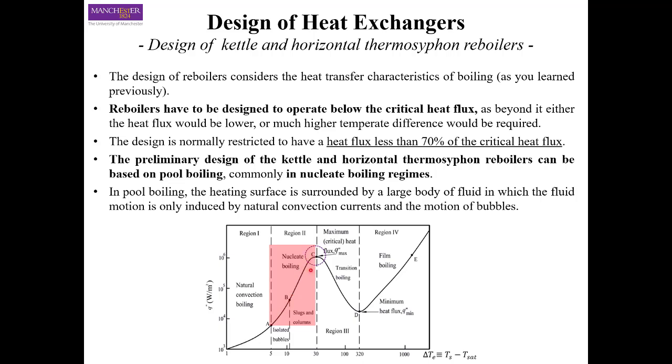When we are talking about pool boiling, just to remind you again, in pool boiling the heated surface is normally surrounded by a large body of fluid in which the fluid motion is only introduced by natural convection and motion of the bubbles. So you don't have forced convection there.